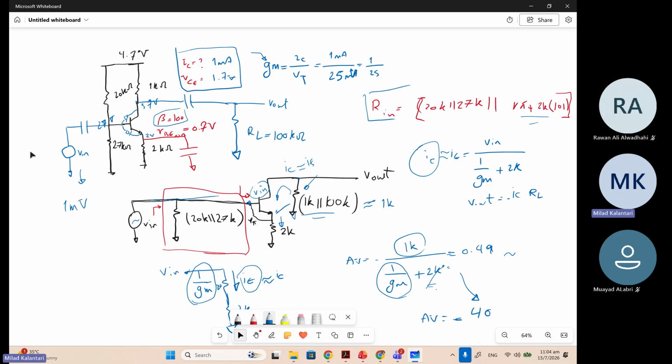So you have this circuit, right? You are trying to apply some input voltage here. That's sinusoidal, right? This sinusoidal thing is actually increasing this base voltage at the positive cycle, right? So what will happen? This base voltage increased. The current of the transistor is increasing, basically, right?